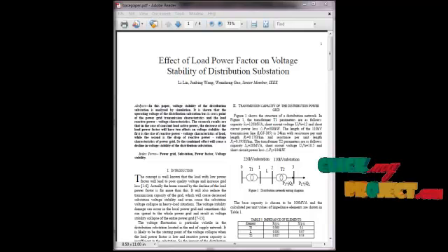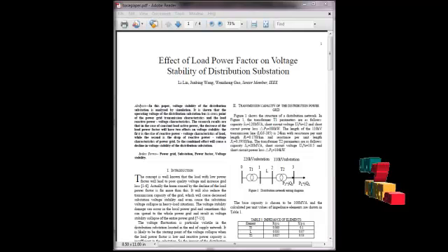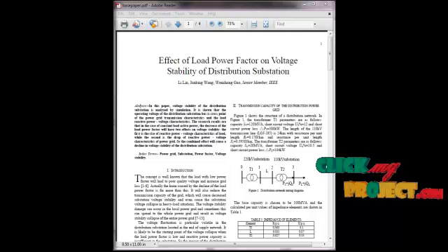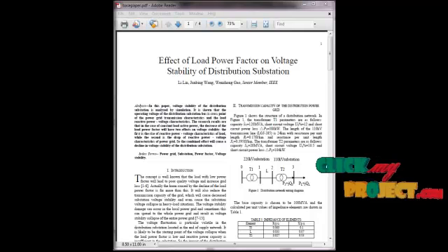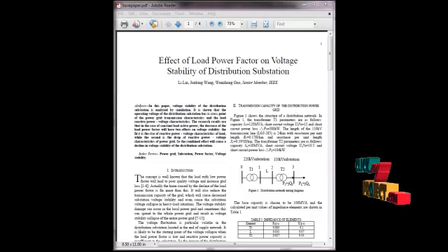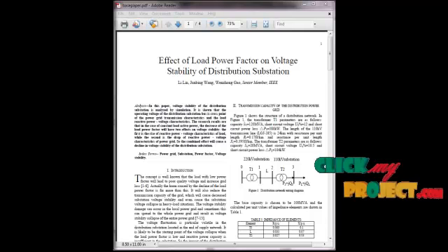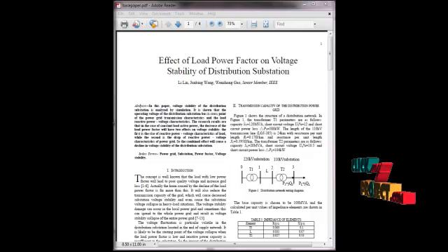The equipment normally used for voltage and reactive power control are on-load tap changer transformers, switched shunt capacitors and step voltage regulators. Such equipment is mostly operated based on the assumption that power flows in one direction only and the voltage decreases along the feeder from the substation to the remote end.